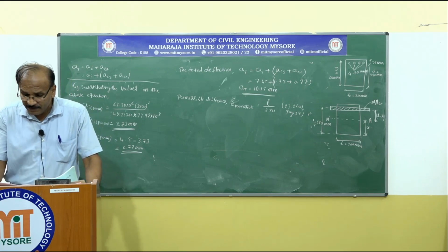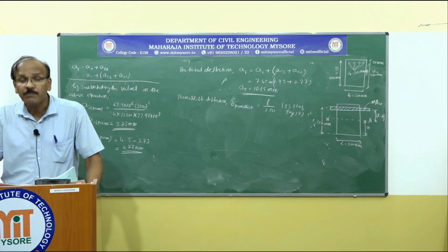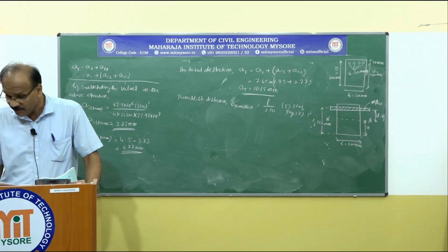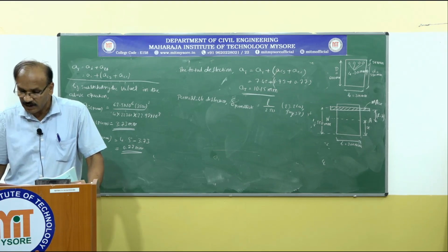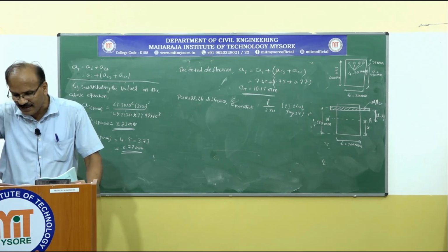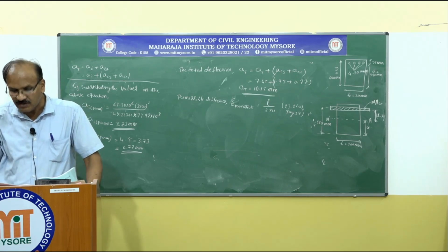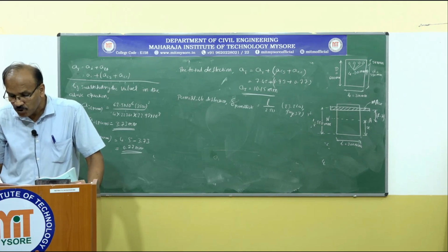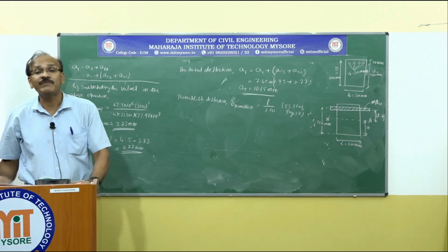So if you open that page in the book, 23.2, under point A, I am going to read out what it is. The final deflection due to all loads, including the effects of temperature, creep and shrinkage, and of course measured from the as cast level of the supports of floors, because we have to measure with some reference, they are giving the reference, roofs and all other horizontal members should not normally exceed span divided by 250.